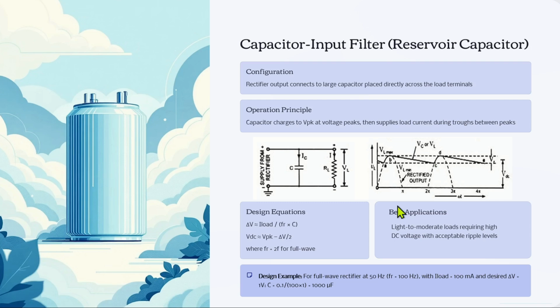The capacitor gets charged instantly, and the discharging time is quite high compared to the charging time. Until the capacitor discharges, the next waveform starts, and whenever the next waveform starts, the capacitor charges again, giving rise to this type of waveform.